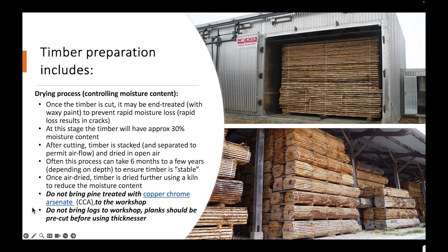The drying process is really important when considering the timber that you purchase. So once the timber is cut, it may be end treated with a waxy paint to prevent rapid moisture loss. So it is important for the timber to dry. However, if it dries too quickly, it may result in some cracking, and that might not be what you're after. When the timber is sawn, initially the moisture content will be at around 30%, so the log is really quite heavy at this point in time.